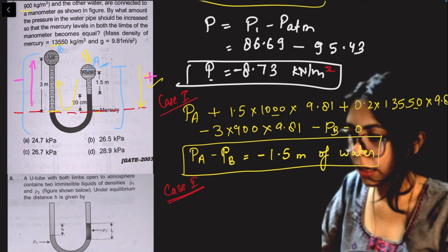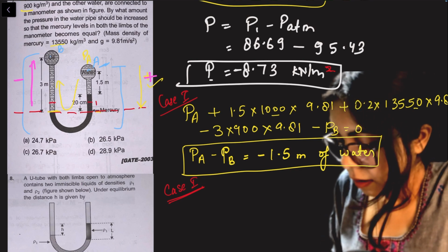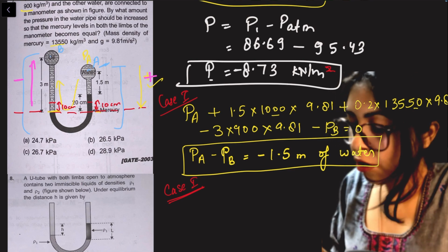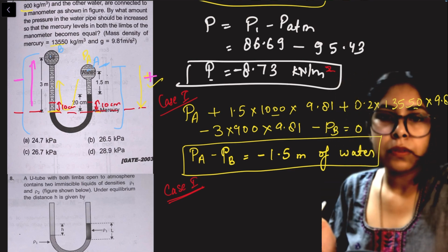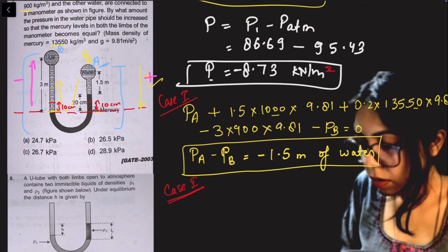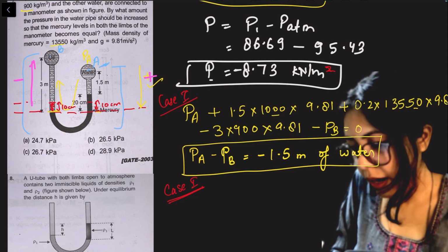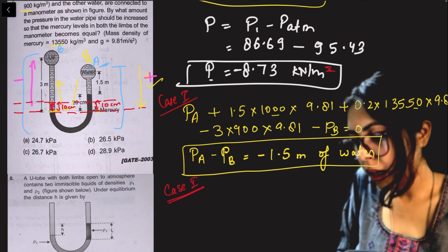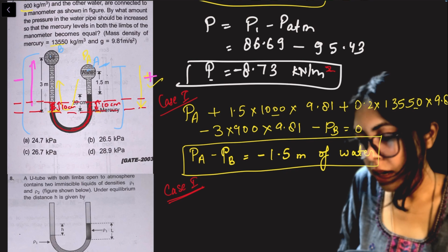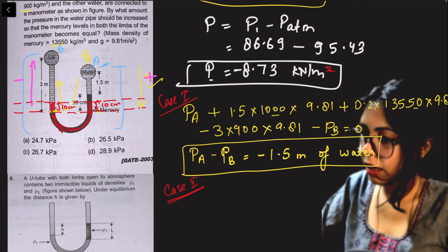they have equalized the mercury level on both sides. Then we know that the mercury will come here and here, 10 and 10 centimeters. Now what I can do is, see, datum we select the line below which there is only one liquid, right. Here also now we have mercury. So in this case, to avoid extra calculation, I can change my datum. Otherwise you can take the same datum, but here I can see that below this everywhere is mercury, right. So if I do the equation in the second case, this is case 2.